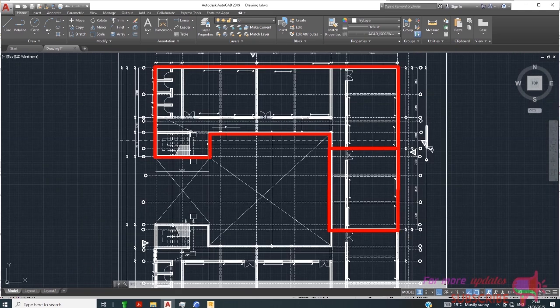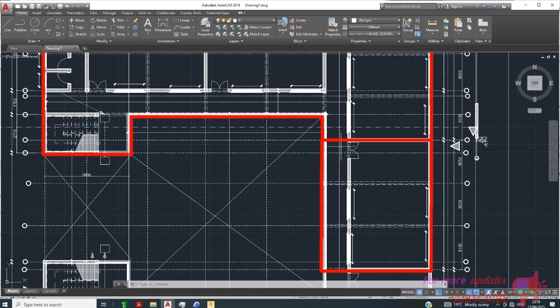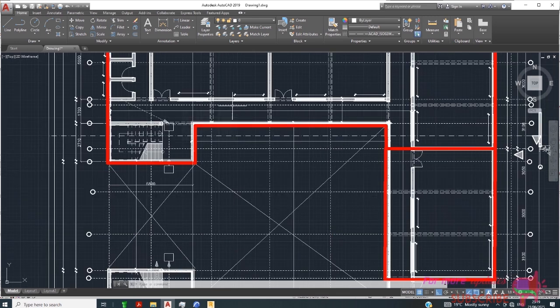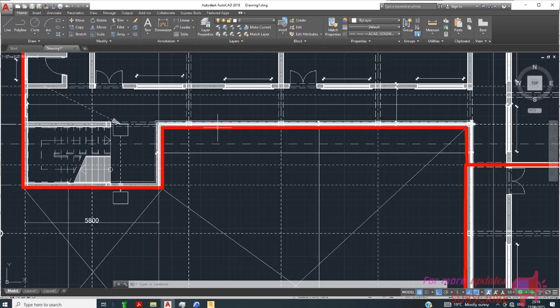Now, for using the Eurocode for schools, because this is a school, I think about the live load in this corridor. Remember, corridors and balconies have a very significant live load. So the live load in this area should be about, not 2.5, about 4 or 3.5. That live load is too much. So we cannot allow that to be a cantilever.